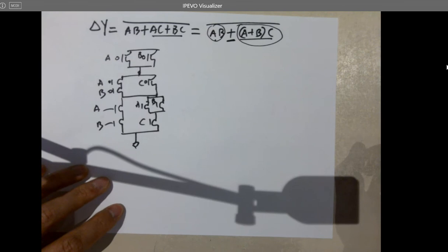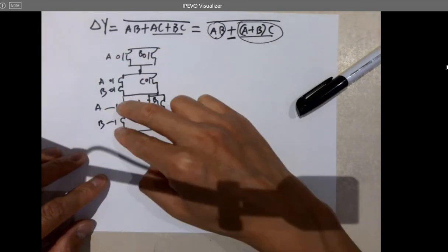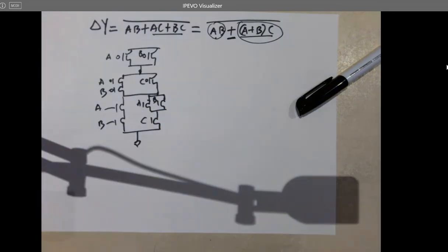So when you run the NMOS part of the CMOS, it's always inverted from the PMOS. Yes. So inverted means if you got parallel here, you need a series here, right? You got series here, you need a parallel here. Yep. So now let's see how we convert it into its layout. Definitely not that straightforward.